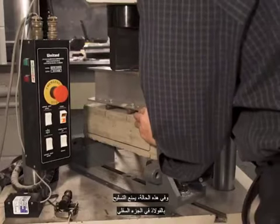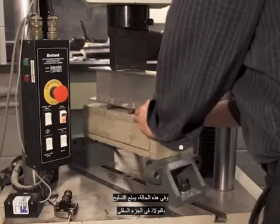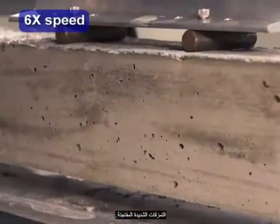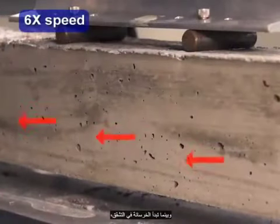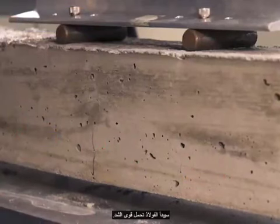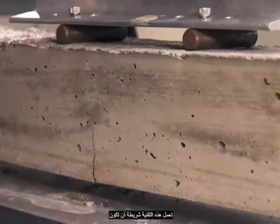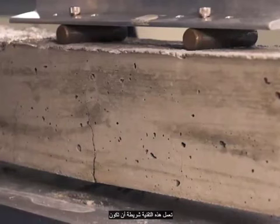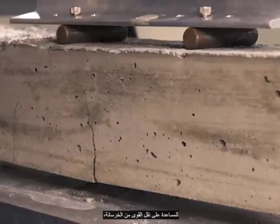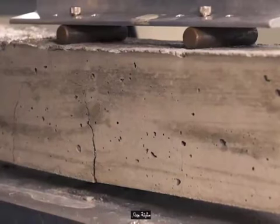In this case, steel reinforcement at the bottom or tensile side of the beam prevents sudden brittle failures. As the concrete begins to crack, the steel will begin to take up the tensile forces. This technique works as long as the steel bars, which have surface deformations to help them transfer forces from the concrete, are properly anchored.